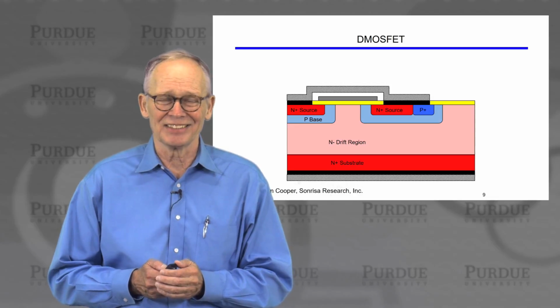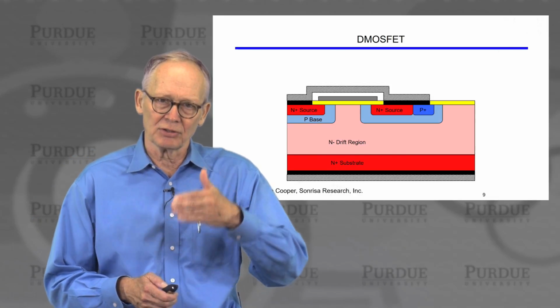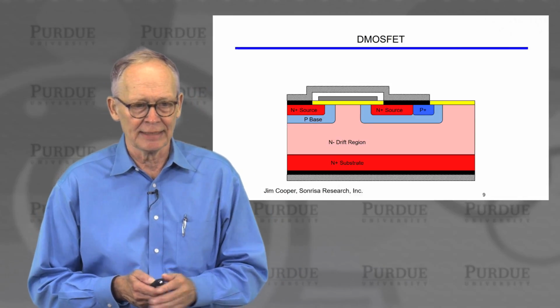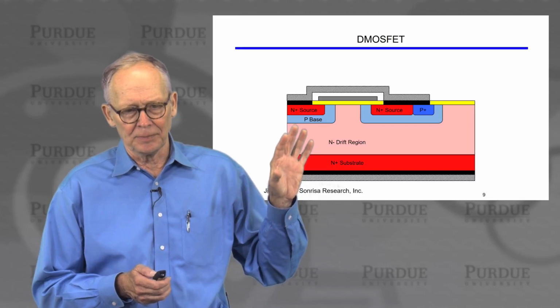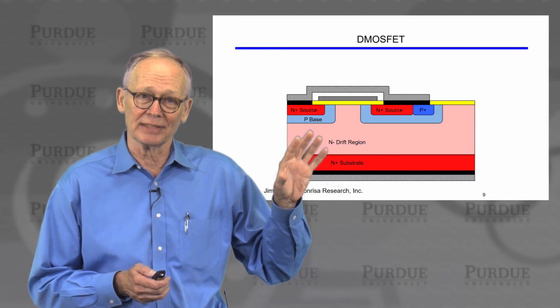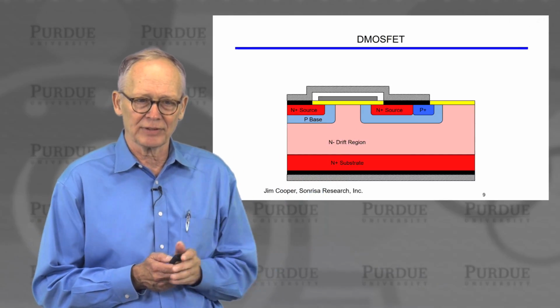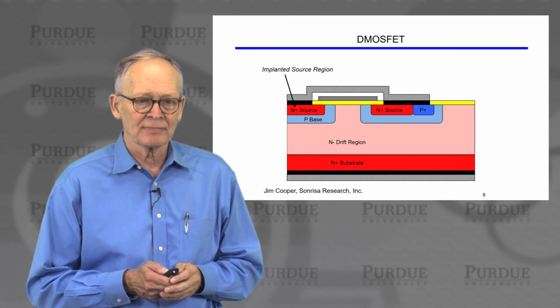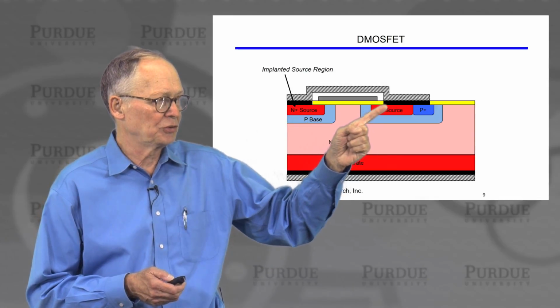Okay, let's look at the transistor itself. So now we're looking at the cross-section of one of these vertical cells in this power MOSFET. And this is what a basic structure might look like. Much different from the MOSFETs we've been looking at. Let's look carefully step by step through this structure. So there is a source region. We see two sources here.